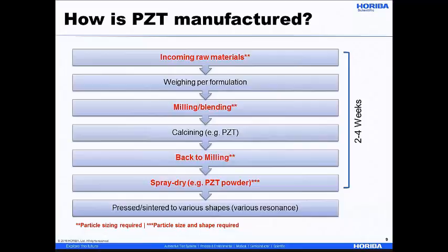After milling, obviously you want to monitor your particle size to see whether it's appropriate for calcination. Once you do calcination, you do milling again, and at that moment again you want to monitor your particle size, and then finally you spray dry these powders before you pack them into different shapes of piezo particle crystals.